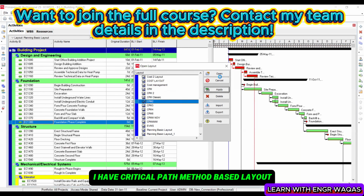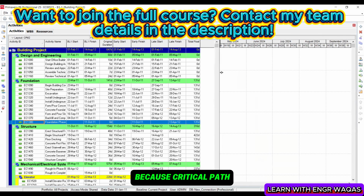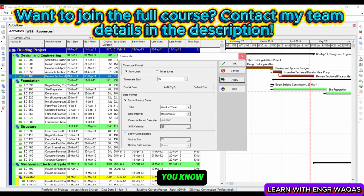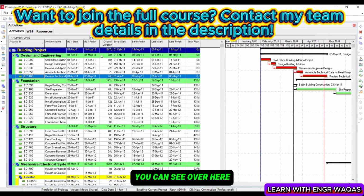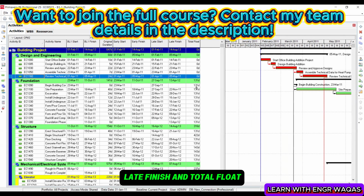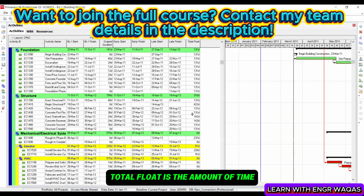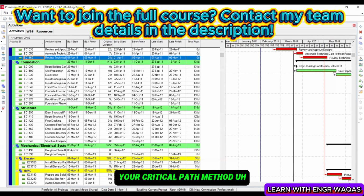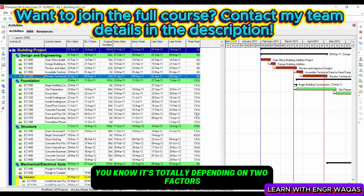I have a critical path method based layout, because critical path method is going to tell you about the things which I'm going to tell you, like you can see over here. Let's say this is early start, early finish, late start, late finish, and total float. Total float is the amount of time an activity can be delayed without delaying project duration. Your critical path method totally depends on two factors: the dependency of your activities, which are the link-ups, and the second thing is the assigned duration. As soon as you change any relationship, your critical path method is going to change.